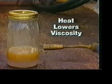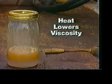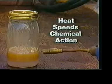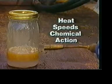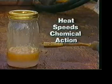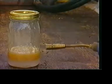Heat lowers the viscosity of oil. This allows the water droplets to move through the oil more easily and settle out more quickly. Heat speeds up chemical action. Chemicals make a rigid film around the water droplets. As heat is applied to the emulsion, water droplets expand and break the film. Water droplets can then merge into larger ones and settle out.